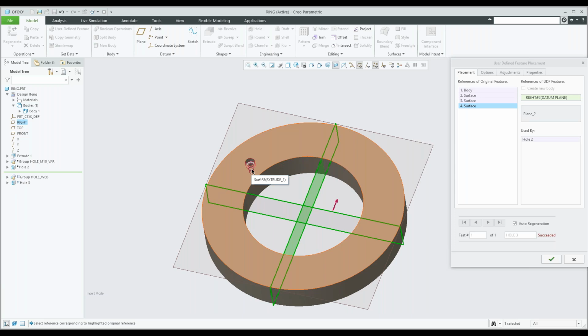The right way was the first one, where you have a datum point or datum max, and that's driving the position of your hole. So don't do this like I've done it here with the datum planes, because the distance from datum plane 2 and datum plane 1 is going to be fixed. And if you use this in another design, it's going to be either outside of the body, or in space or something like that.